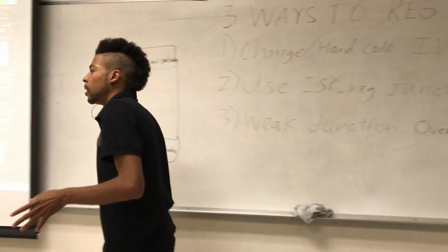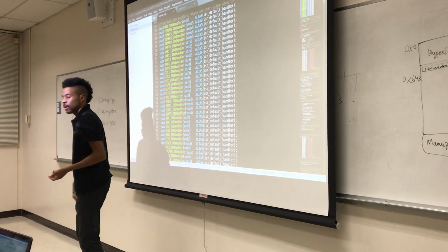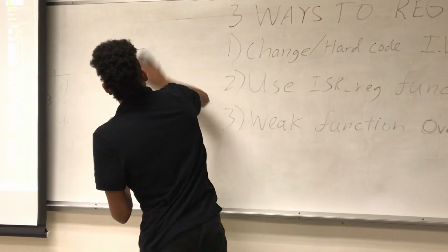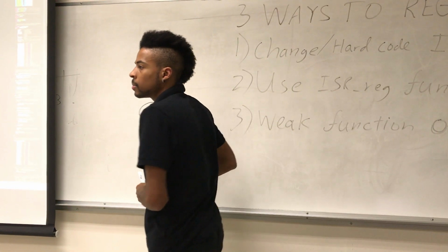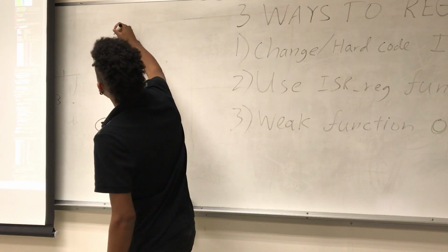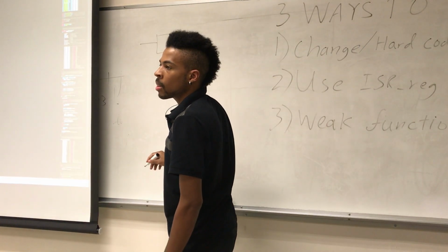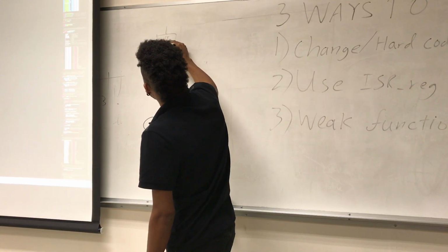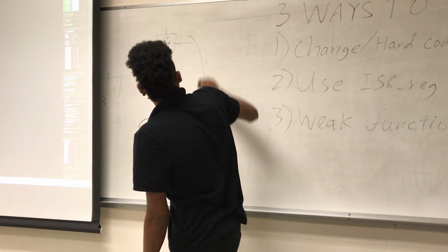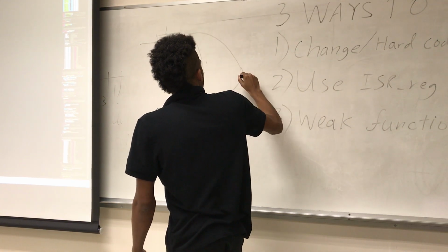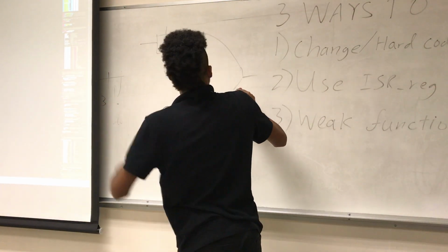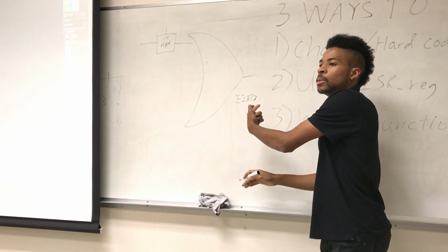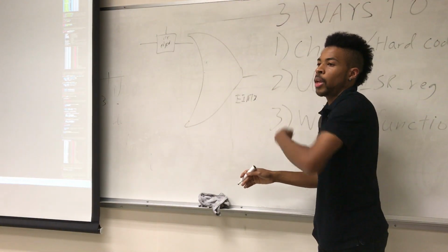It's not the exact diagram, but here's a really easy way. Let me erase this real quick. It's a simple implementation. You have your pin, and you have some edge detector. This can also be cleared, so you can have a clear pin here. This would be the edge detector for that particular pin, and then it goes into a big OR statement. That's pretty much the interrupt 3 flag to say, hey, system, we have an external interrupt 3 condition.